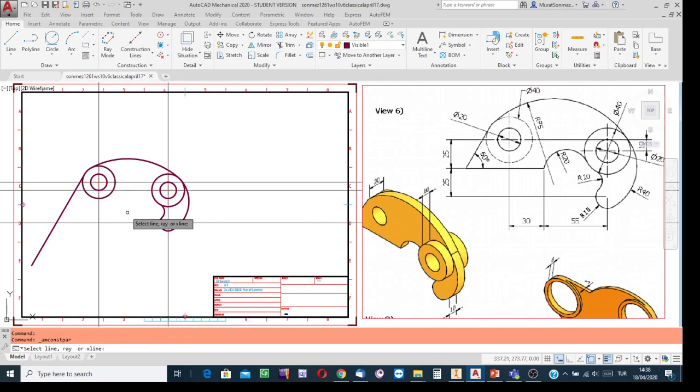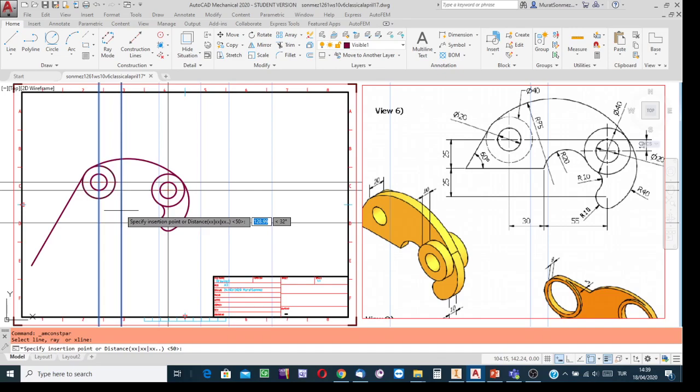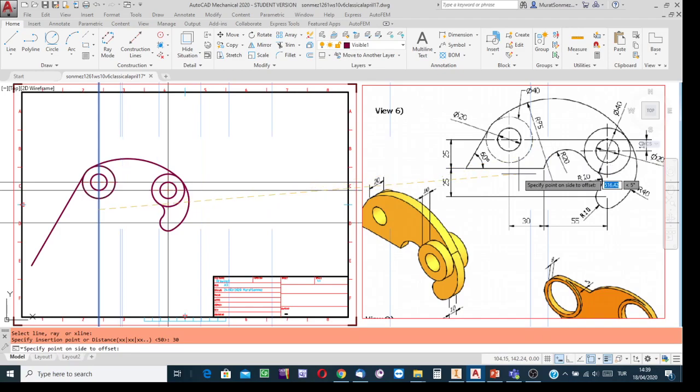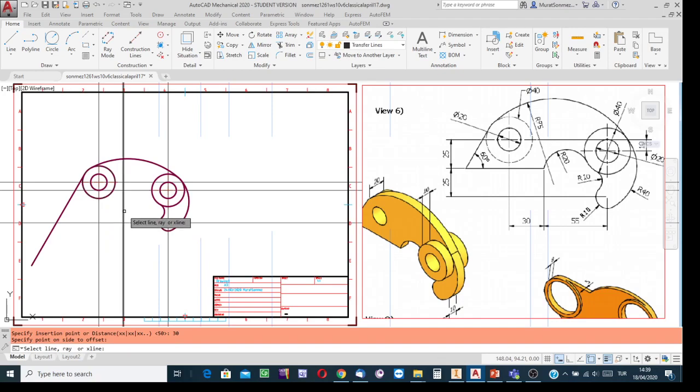And then I know that relative to the vertical transfer line, it passes through the center of the first group of circles. The reference for this terminal point is 30 units. Write 30 into the box, press enter, and then I know that that point is at the right side, so move the cursor to the right and then click. Yes, I am sure this is the line along which to have the terminal point of this line.